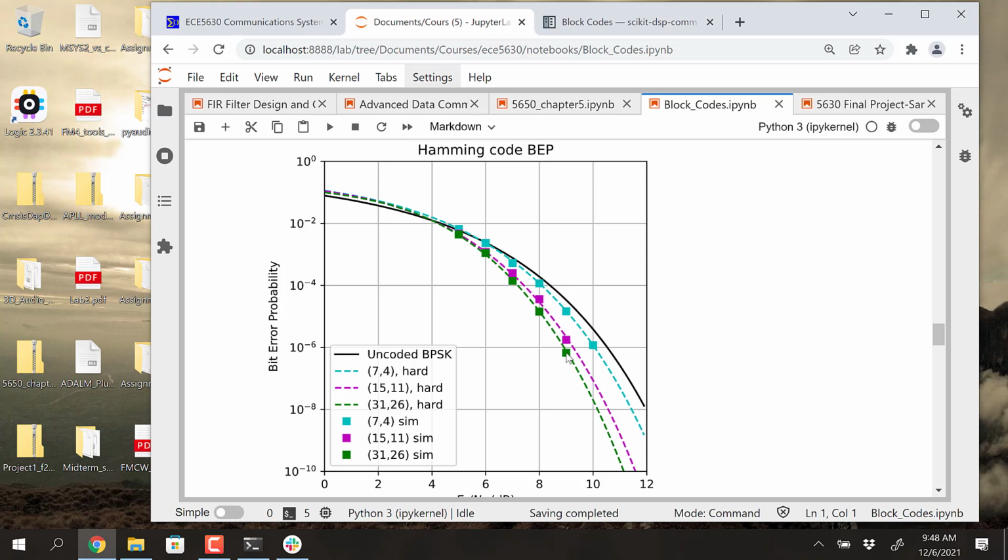Because I guess, if you're sending extra code bits, those code bits have their own bit error probability. So smaller codes have some efficiency there, right? Right, and that's what Hamming, I think, was studying. This is a longer code, but LDPC, low-density parity check codes, take this and drive it to thousands. They just become huge integers in those two slots for N and K.